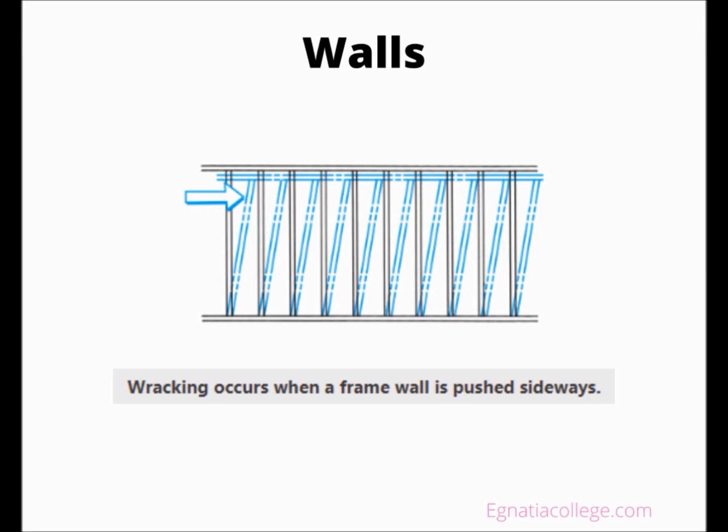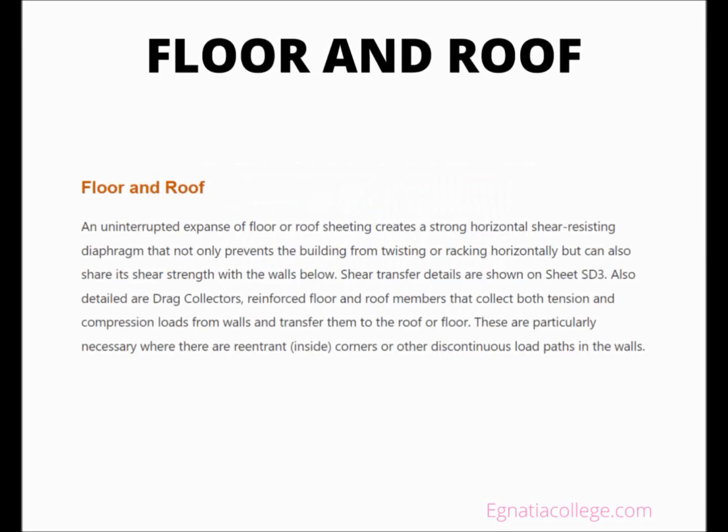A critical design consideration is that the shear wall sections stack vertically, with upper-level shear walls occurring directly above the shear walls below. On sheet S7.2, there are references to strap hold-downs connecting each story to the story above, holding the building together vertically, and transferring shear from floor to floor. Details of these connections, including the straps, are included on sheet SD2.